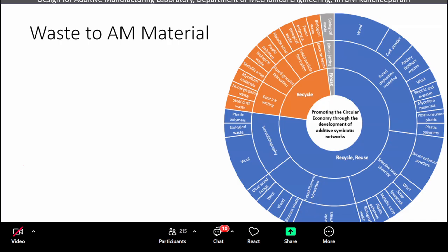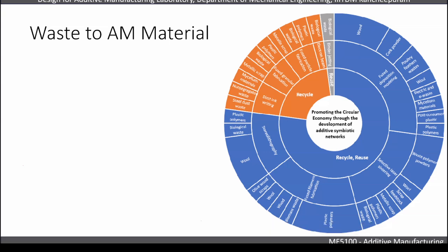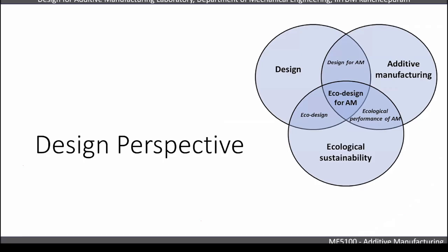Even the fumes and vapors that are developed in FDM-based 3D printing using ABS are far less environmentally sustainable compared to PLA. PLA is derived from natural resources, so it's biocompatible, and it's also a biodegradable polymer. So it's very important that we use PLA for most of our applications. That's the reason why additive manufacturing with polymers, especially PLA, is more sustainable. This is from the materials and sustainability perspective.